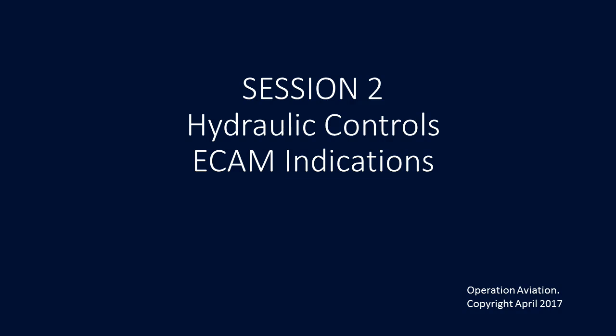Now, what about the reservoir pressure warning? The reservoir is normally pressurized to prevent pump cavitation. Okay, so that's pretty clear. We need to make sure we maintain a good constant pressurization to avoid that problem. So the message here, we want to make sure we monitor that air pressure. It's going to show low air press, and that will appear in amber along with the ECAM caution message when that reservoir pressure drops below the normal pressure. Your fluid temperature warning: the reservoir overheat indication appears in amber. It's going to show there when the fluid temperature goes too high.